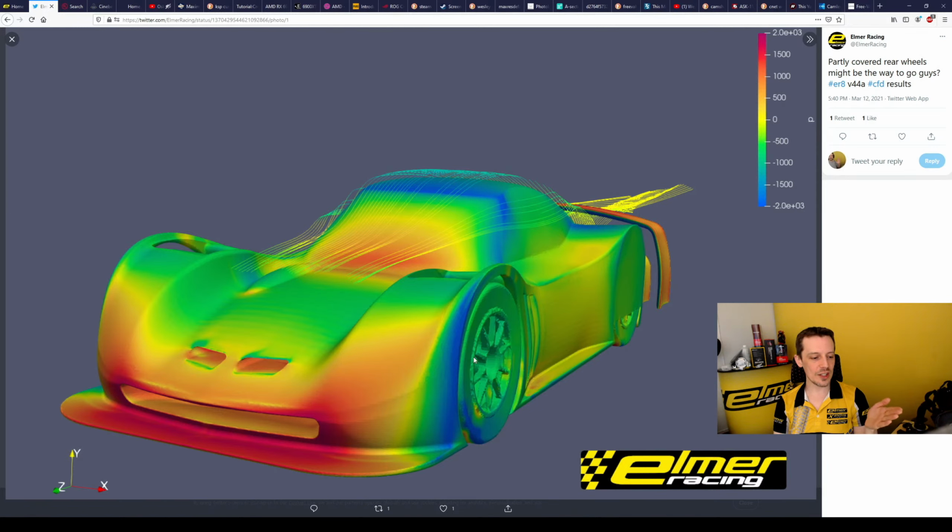So it is a full mid-engine setup basically. The Opel GT does have the engine really far back compared to the front axis anyway, and we've been able to push that backwards a little bit more because we don't need any clearance behind the rear of the engine. The engine just bolts directly through the firewall, so we don't even have bolts in between there, but the bolts for the engine mounting go through from the inside of the car through the firewall to mount the engine to the chassis, so it's as far back as possible. And it is in fact a mid-engine, so there's no part of the engine that sticks out in front of the front axis of the car. So yeah, this is for the plenum there.